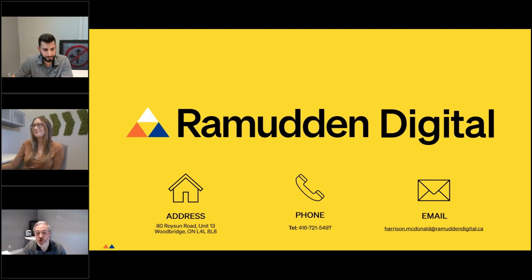So the short answer is we don't know. What we know is what York has gone through as far as the review. The signs are MUTCD compliant. They are NTCIP compliant, the communication protocol which MTO uses for all their ATMS. And the LEDs and the BMS themselves are NEMA TS4 compliant, which is the BMS standard for North America, and EN 12966 compliant, which is the European LED standard.